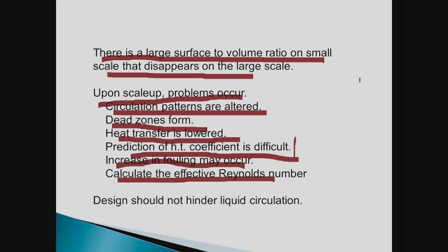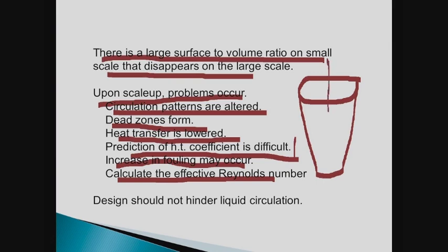In one reactor I ran into, it was very symmetric. Basically, as I recall, it was sort of like this. And for some reason, it fouled only on one side, basically. I think the feed stream came on this side and never really effectively went over here. Only in the bulk did it go over. And it was really strange that the fouling occurred on one side of the reactor and not on the other.